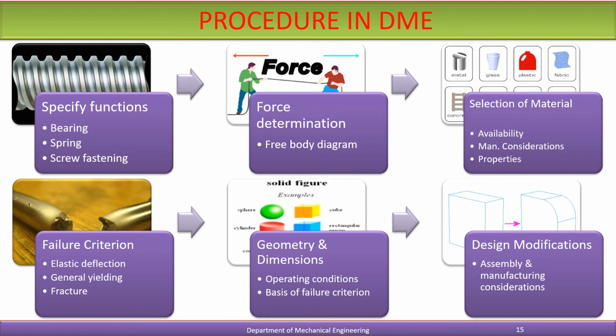Here the shape of the machine element depends upon two factors: the operating conditions and the shape of the adjoining machine elements. For example, an involute profile is used for gear teeth because it satisfies the fundamental law of gearing. A V-belt has a trapezoidal cross-section because it results in wedge action and increases the force of friction between the surfaces. So this factor is also important.